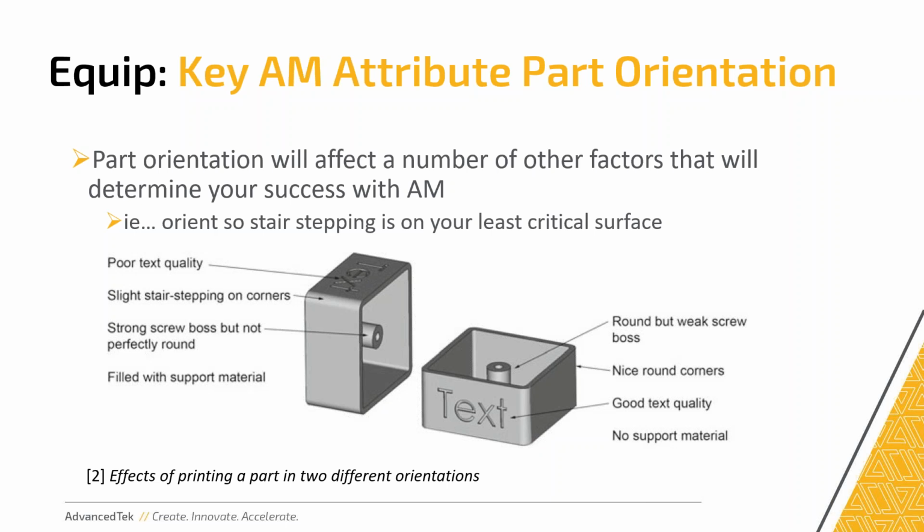If I build it standing on its edge, I'm going to have a little stair stepping on my rounded surfaces. My screw boss might not be perfectly round, but it's going to be stronger if I'm going to be screwing onto it. However, the internal cavity is going to fill with support material.